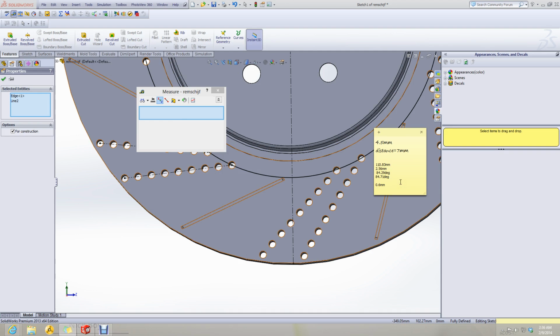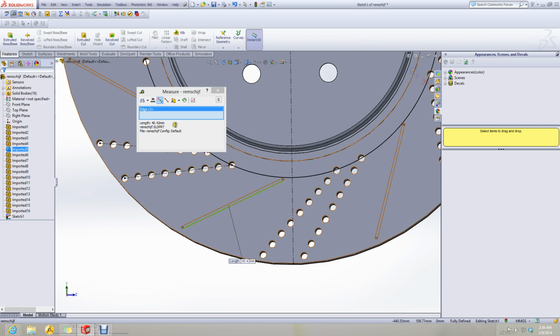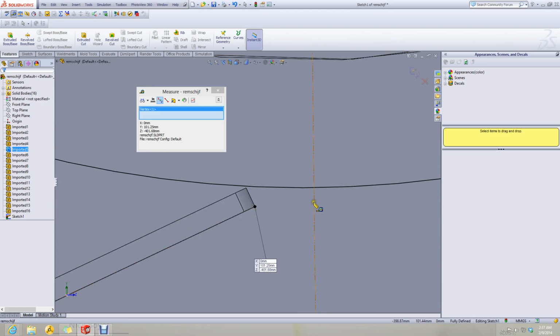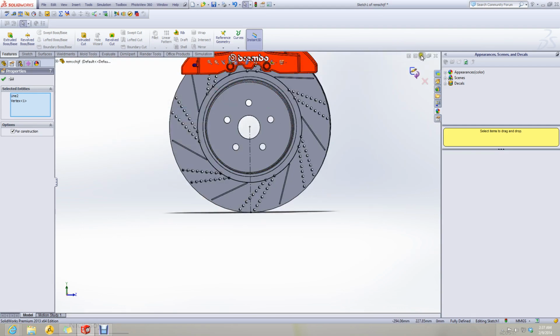0.6 mm depth, 0.94 mm thickness, and approximately 66° angle. And total length is 40 millimeter. Let's take it 40. And its distance with this line is 2.84 millimeters. Let's make it now.